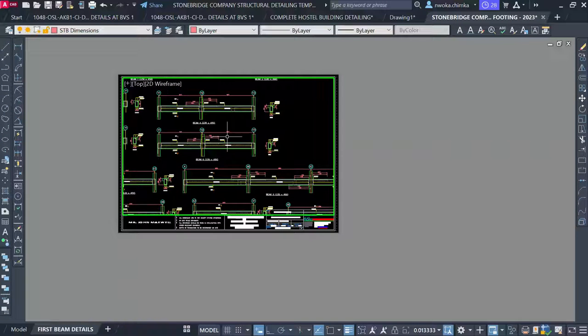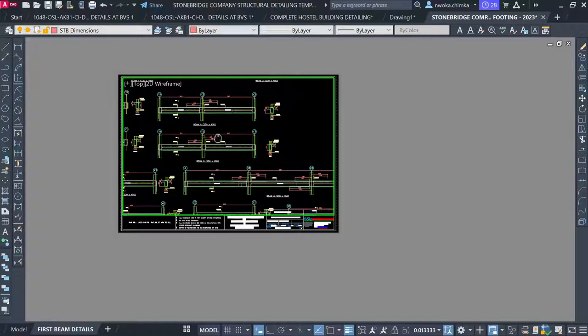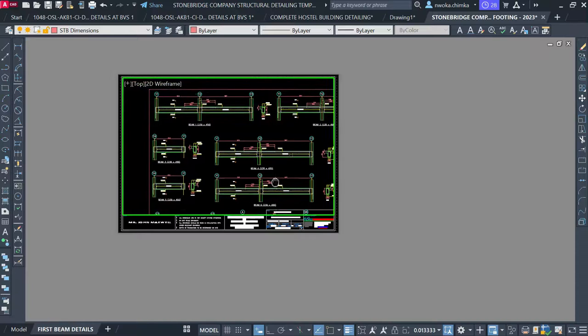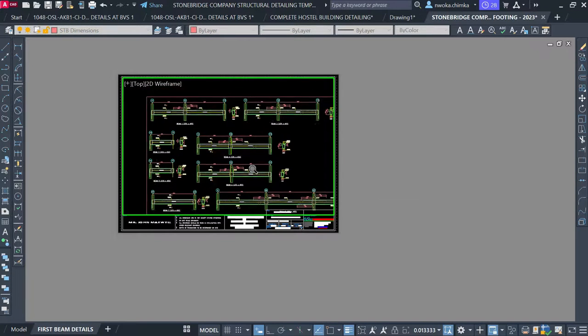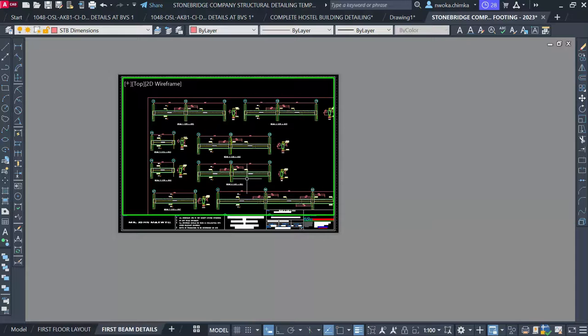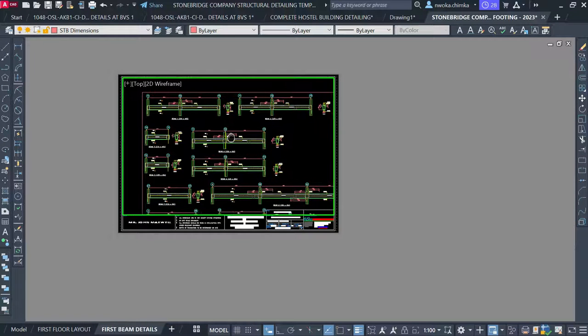Okay, 75 will not show all the beams. So you have to locate the ones that it will show. Looking at this, I don't want 75. Let me use 100. So Z, enter, 1 all over 100 SP. Okay, 100 is able to show. Yes, it will be very visible if we print.